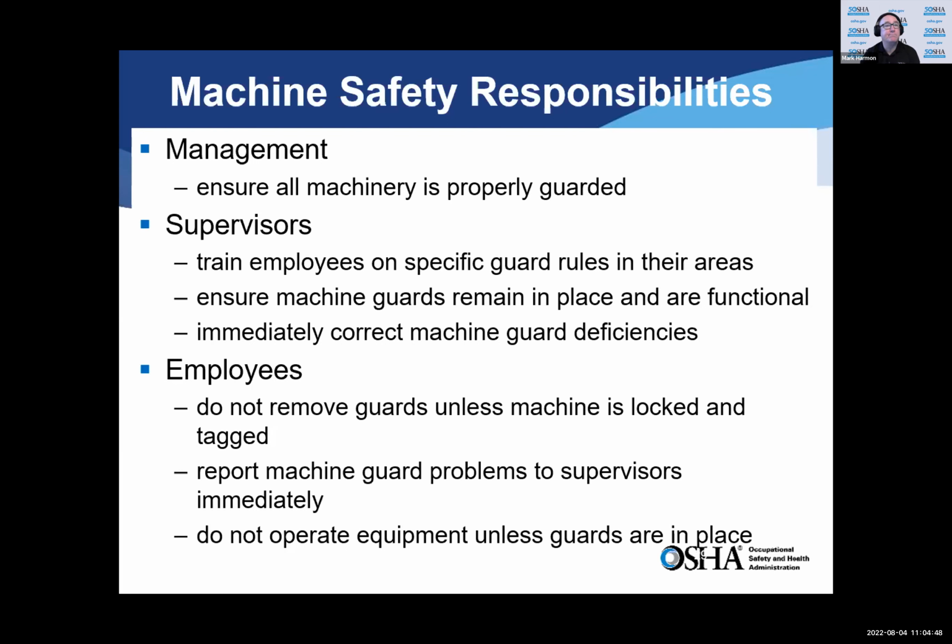Employees sometimes will turn the machine on and they start working. They should know what guards are required or what safeguarding is required, and make sure that the training of these employees and operators is completed, and that if the machine is not in a serviceable condition, the employees should know not to use it, right? You lock it out, put a tag on it, say this is not to be used until it is maintained or serviced properly.